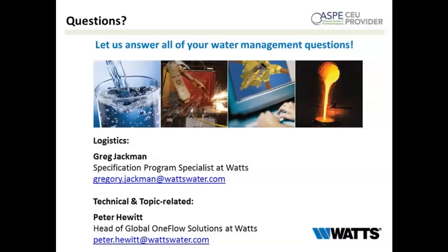Okay. Next question. If we place carbon filtration in front of TAC system, we will be removing chlorine, which is a disinfectant for the water system. Would we then need to treat the water for biological protection?